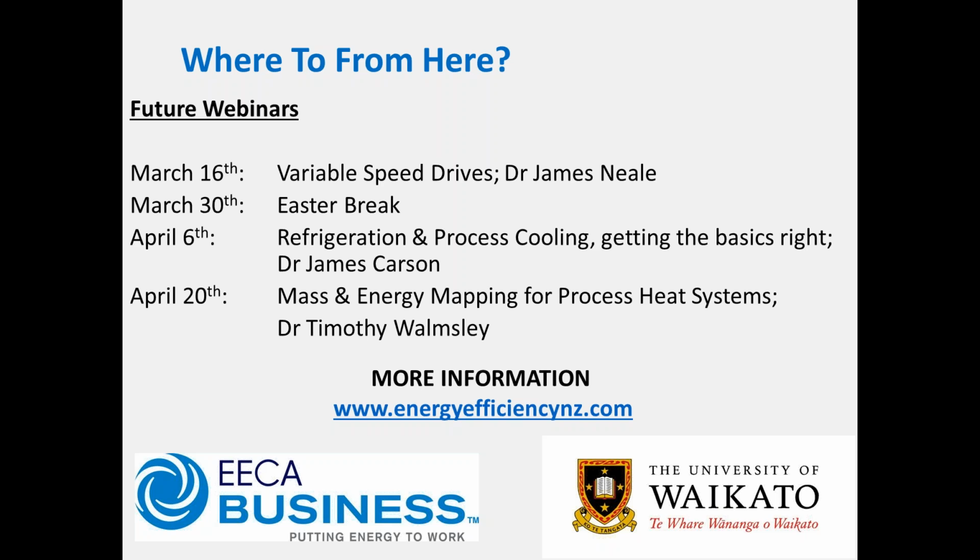We've just had a question, Dave, that's come through from Pramesh. How common is online dissolved oxygen monitoring and blowdown control in the industry? You mentioned it's obviously useful. Automatic blowdown control is extremely common. In fact, I'm struggling to think of any industrial boilers I've seen in the last few years that didn't have an automatic TDS type controller on them.